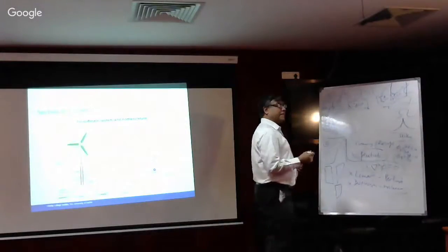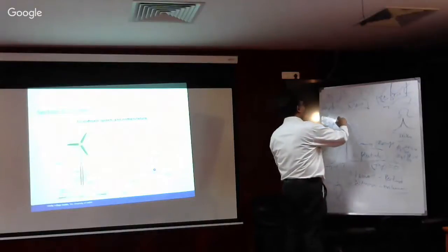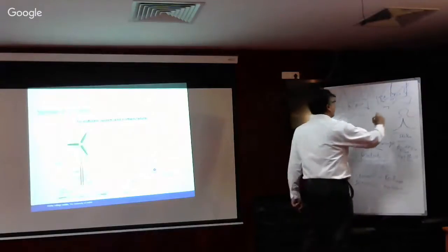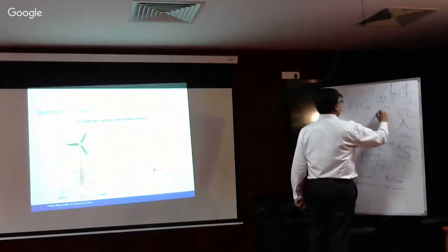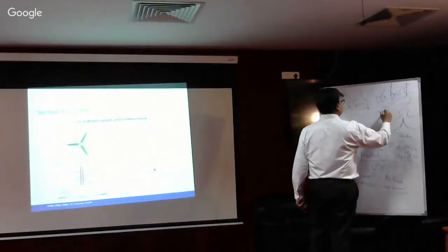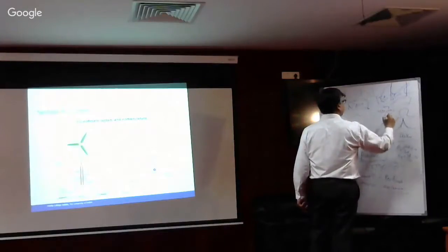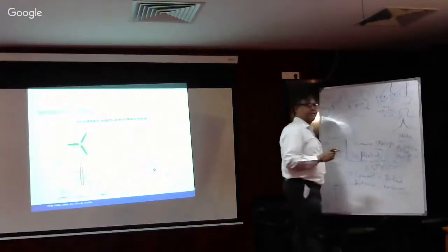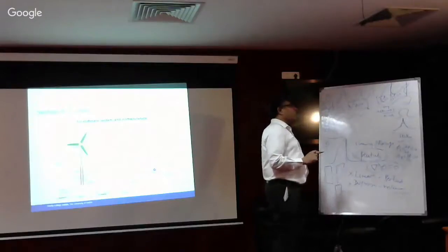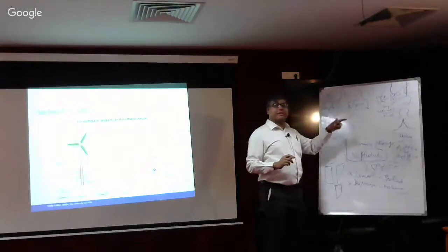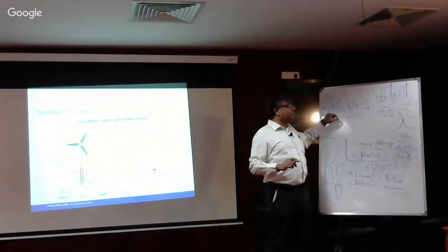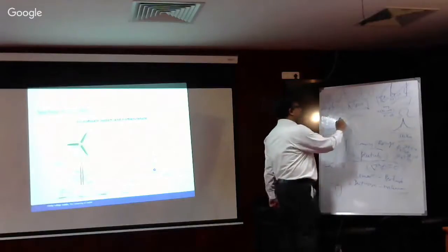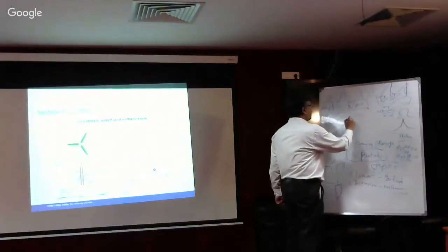So obviously, let's say we consider a wave which is propagating like this, in space and time. We were representing any particular function like the velocity u by kx minus omega t, or we could say also x minus ct, where c is the velocity of propagation of the wave. The velocity of propagation of the wave and the velocity of the fluid particles are very different. The fluid particles are propagating like this. So at any point, you have u and v velocities.